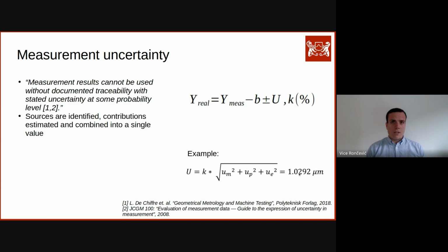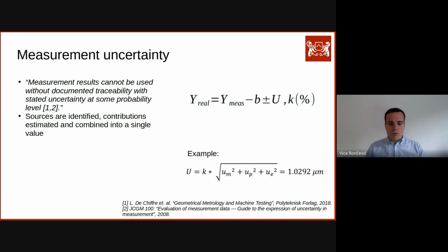The reasons are that the CMM is by far a superior, larger, more expensive machine on air bearings with very controlled movement. And then of course the measurement lab has always been at 20 degrees Celsius, which has a big effect. When you do proper measurements for statistical process control, you are always required to leave your samples in the lab to cool down, or acclimatize to the lab environment, so they can also be roughly at 20 degrees Celsius, and you make that kind of control before you actually approach the measurement itself.